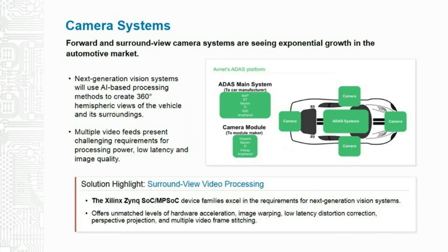Okay, let's take a look at camera systems. Camera systems are the only ones right now that can reliably identify not only that there's an object, but what the object is. When combined with optical character recognition, the car can tell what the posted speed limit is. It can tell if there's a temporary construction speed limit or an accident or fog alert from an overhead sign. Again, this involves machine vision and in some cases artificial intelligence.